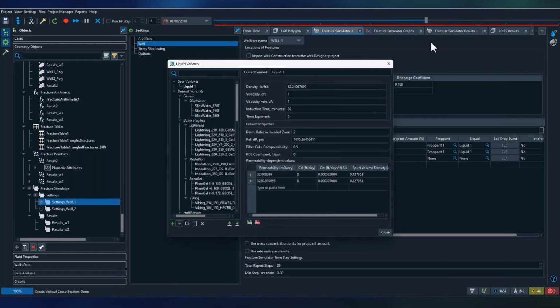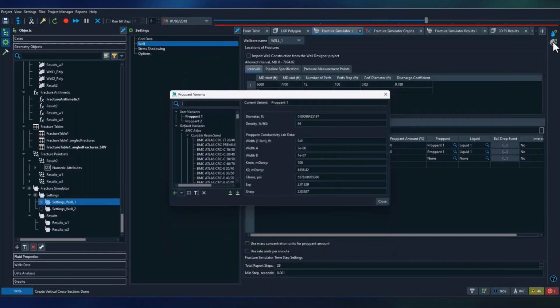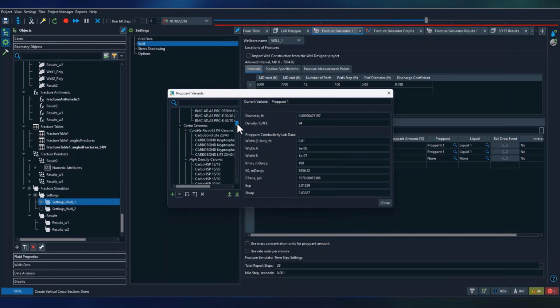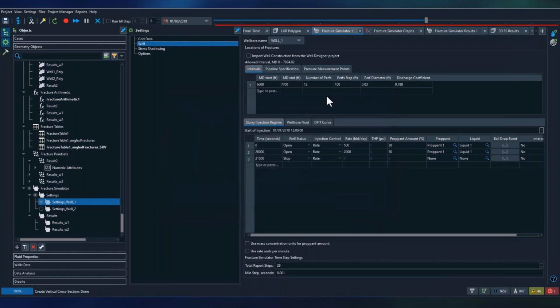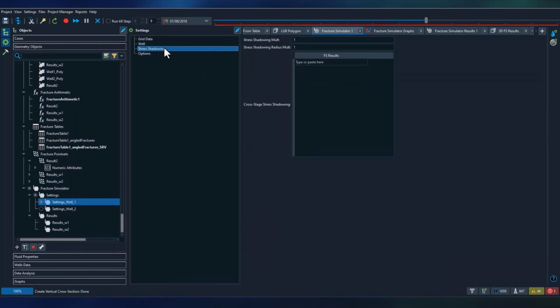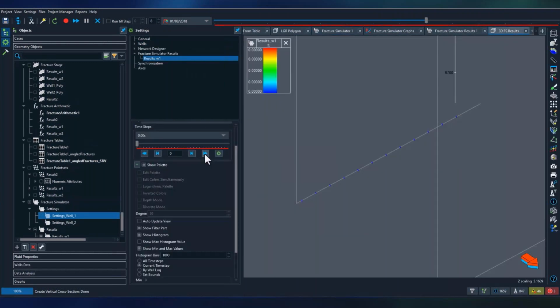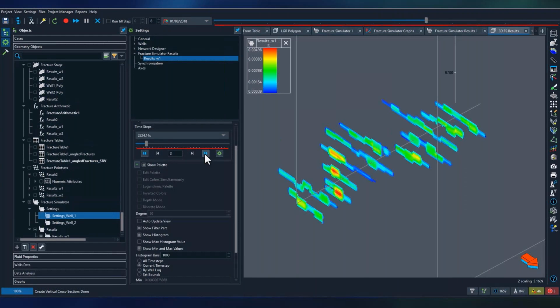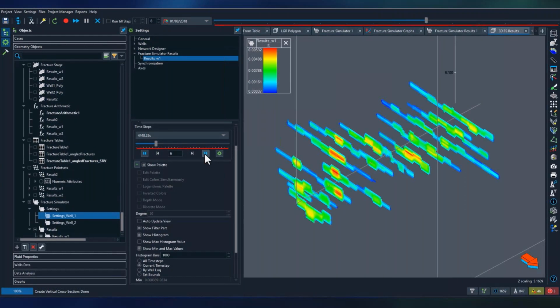Fracking fluid specifications such as proppant and pumping schedules play a critical role in the simulation of the fracture propagation. This is a built-in library in which the fluid and proppant properties can be chosen from, or the user can specify their own specifications. It is also possible to specify the PVT properties of the slurry to take into account the influence of the slurry leak-off into the reservoir, considering the shadowing effect, and to employ different models for proppant velocity.